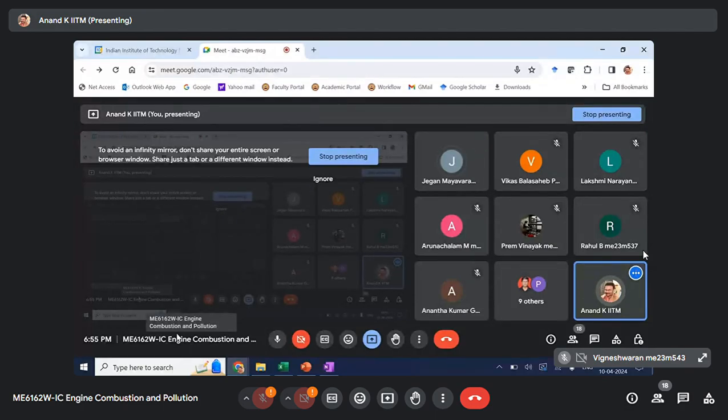Whatever affects delay time is going to affect the formation through this source, because at high load you will have a shorter delay and less over-lean flame blowout region, but at low load you will have a longer delay. You will have more lean flame blowout region.